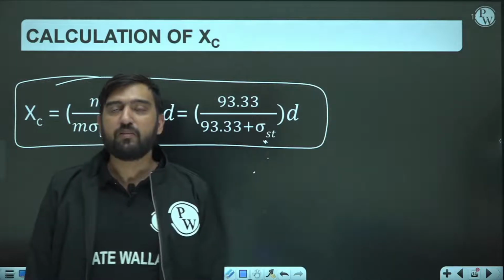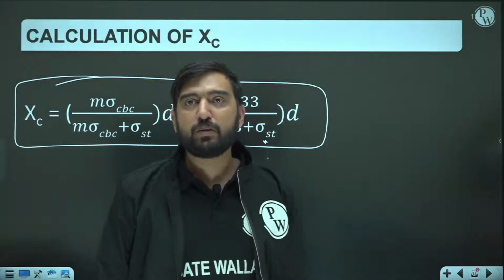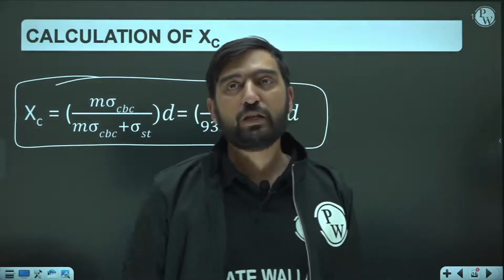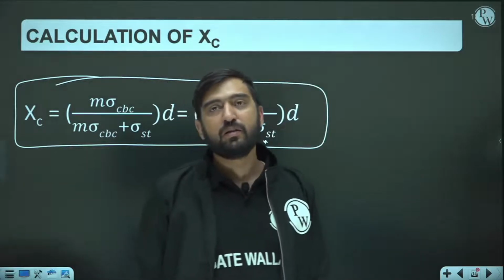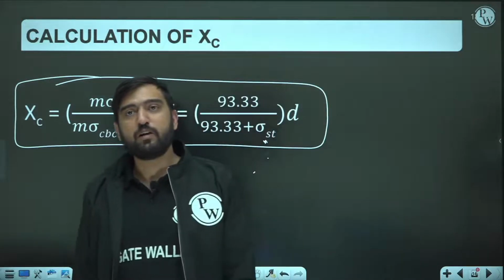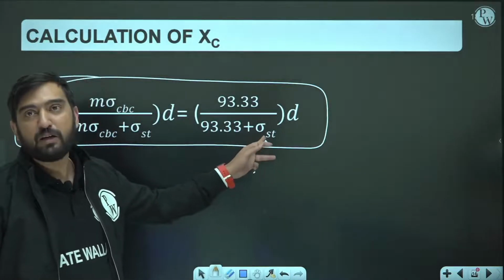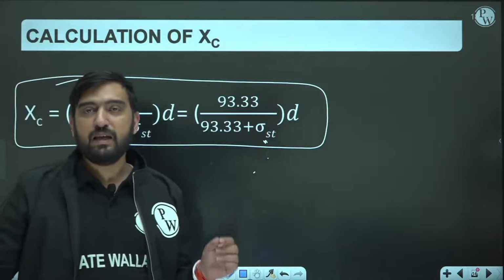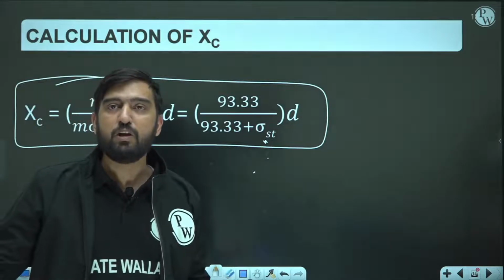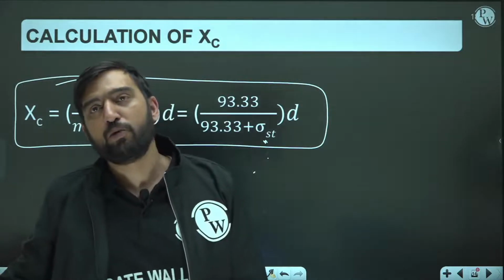K was 700 upon 1100 plus 0.87 Fy. So that value of K was depending upon the Young's modulus of steel, which is constant, and on another thing, which was grade of steel. So here as well you can see that results are depending upon the grade of steel. So XC value is only going to depend on grade of steel. I hope you are getting it.